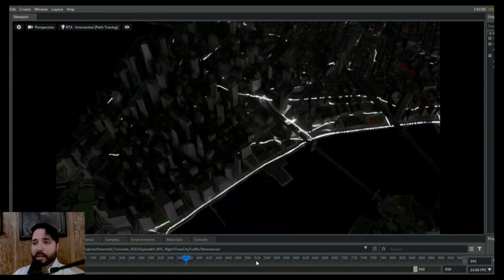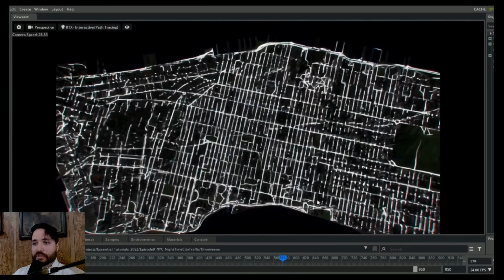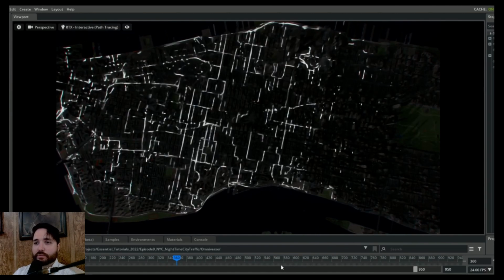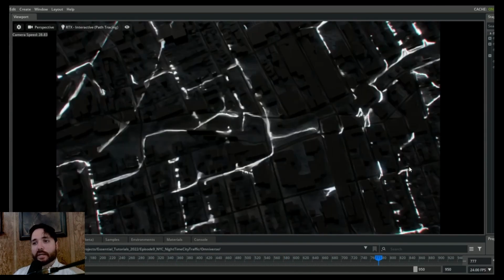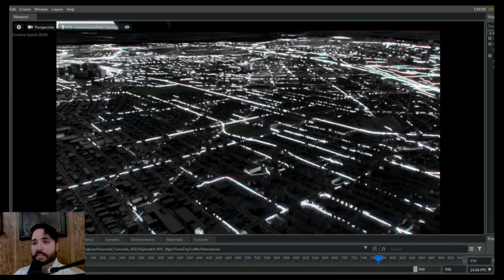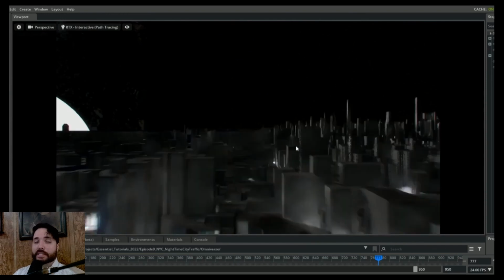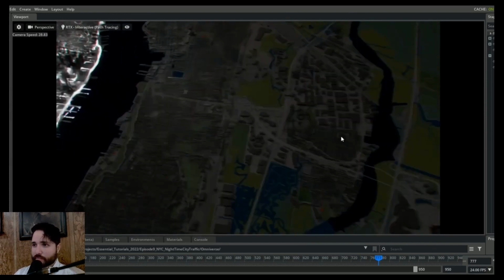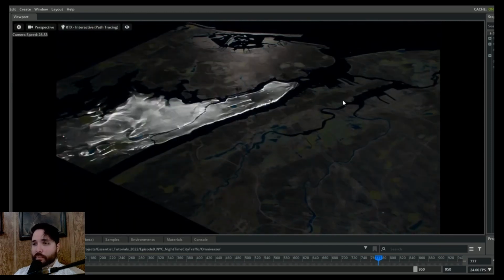So here you can see a behind-the-scenes look on how the Omniverse project file I used on that final animation. You can just see how large the scene actually is and how fast and responsive everything remains. The bottleneck for me was actually the large Alembic file sizes, which ended up being 100 plus gigabytes. And it slowed me down only because I was reading those files from a network drive instead of a local SSD. So that's just something you want to keep in mind when you're working on it.